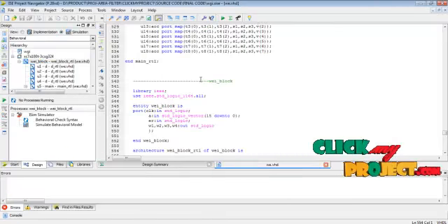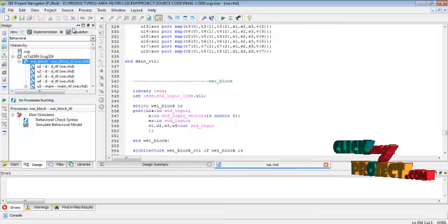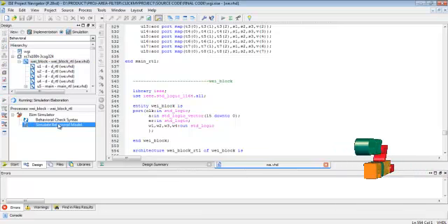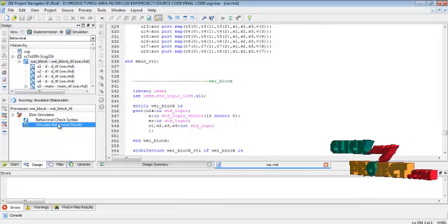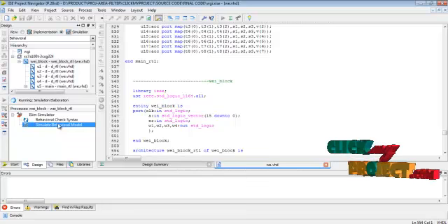Our program is developed in VHDL language. Then we select the weighted update block to select the simulation work, then select simulate behavioral model. We run the process for our processing result, then open the Xilinx ISim project.